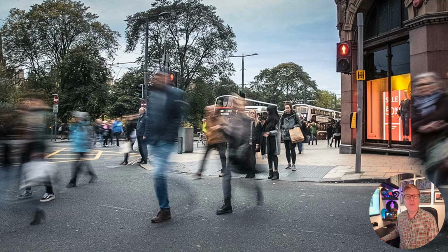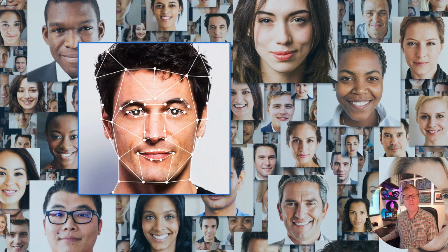The vast majority of traffic signal installations only account for the presence of pedestrians once someone waiting to cross has pressed a push button. With the changes in the hierarchy of users, and to encourage people to walk or cycle, it is therefore increasingly important that UTC systems are equipped to cater more appropriately for pedestrians and cyclists, by understanding that all the people leaving a tube or railway station, shopping mall, office building, etc., will be arriving at a crossing in the coming seconds.